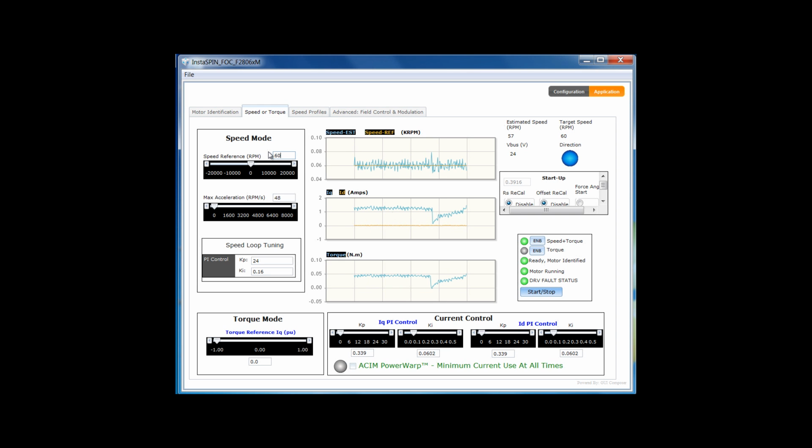Now the next thing I want to do is obviously try to go slower. I'm going to remove the load from the shaft. You'll notice the torque signal immediately starts going down. I'm removing my hand from the shaft because I'm using a capacitive touchpad, and when you touch the motor, the capacitive touchpad actually stops working. So your voltage changes and the mouse doesn't respond to you.